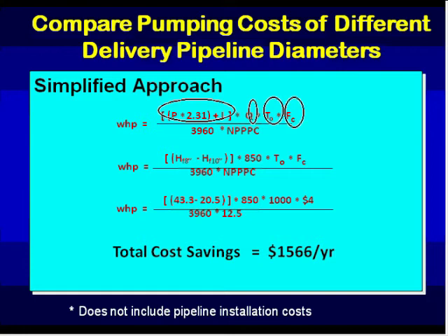We're going to do this a shortcut by just looking at the differences here, by the way. In our initial installation, we had 43.3 feet of head loss in the pipeline, and we had in our new one with the larger and multiple size pipelines 20.5 feet. So what we really get here is the difference in water horsepower hours required because of the friction loss in the pipeline. All other things that we had associated with our system, basically, we're assuming that they're going to be the same. So they're not going to enter into the mix.